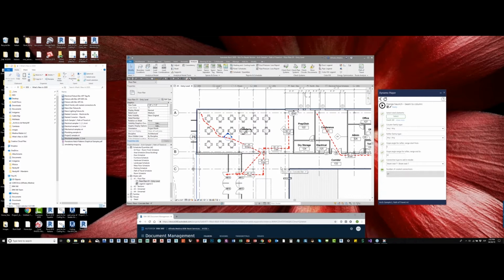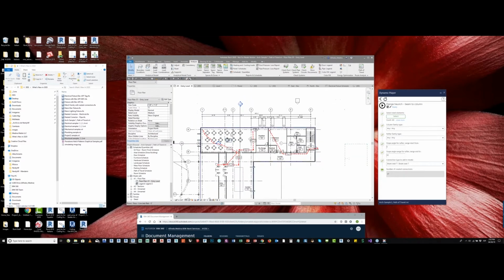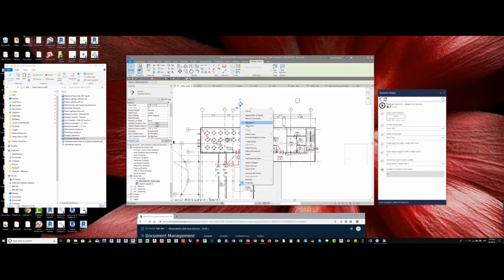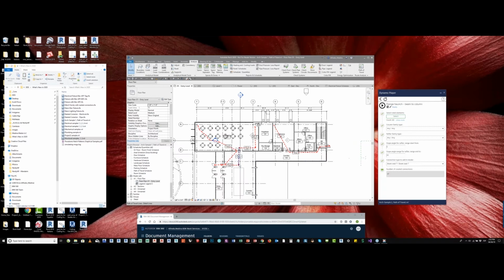Any other questions? Yes. Does the travel path tool connect between levels? No. It's only for floor plans. It doesn't go up stairs or ramps. And when you go to a section, because I tried that, the tool is not even active. Look at this. If I go to a section, the tool is grayed out. Okay, so I think it's perfect for egress plans, basically.